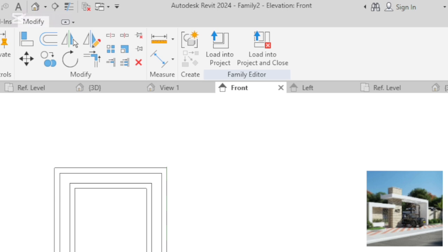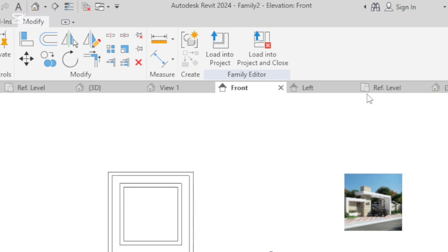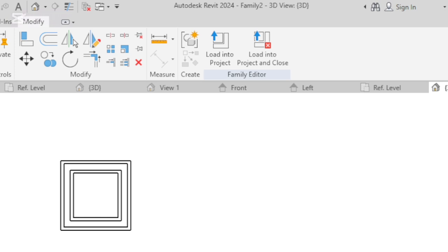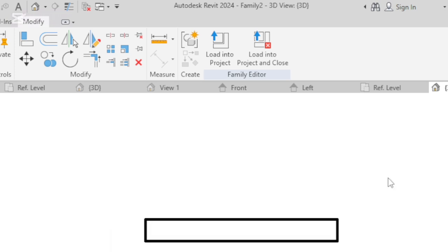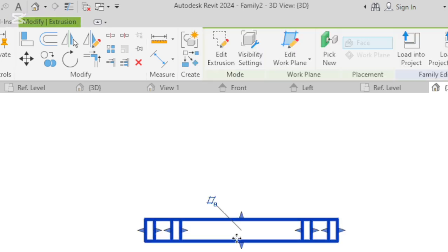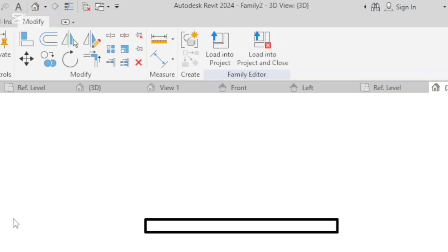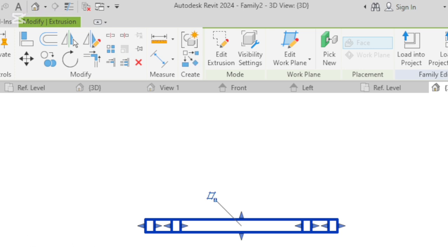You can go to floor view as well to check what we've done. But let's take it on top view. 3D view, top view. This is what we've gotten. So we can still change highlights, change the thickness of this span here. I want this span to be up to 100 or 150. Let me say 150. This is the thickness here, 150. You can say we want it to be 100 and make it 100.